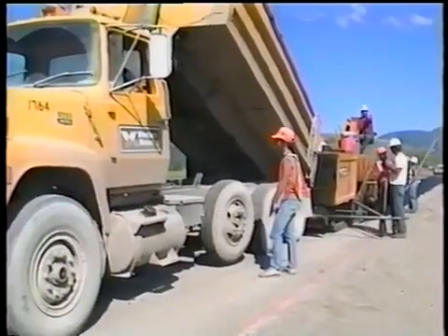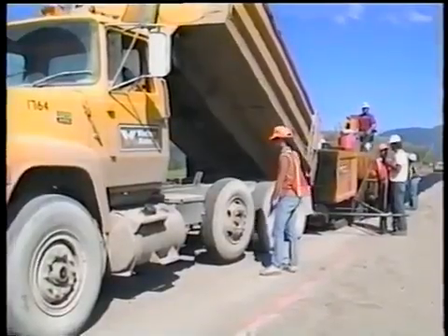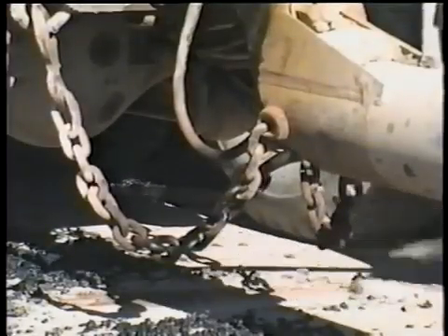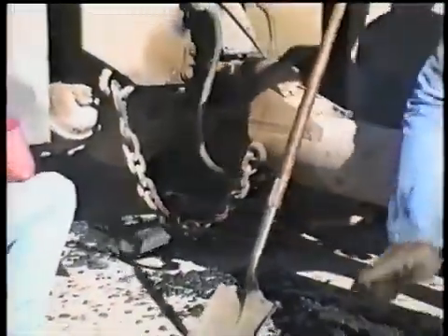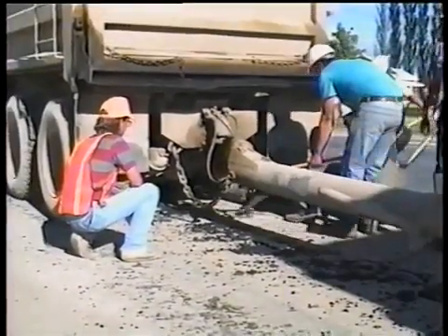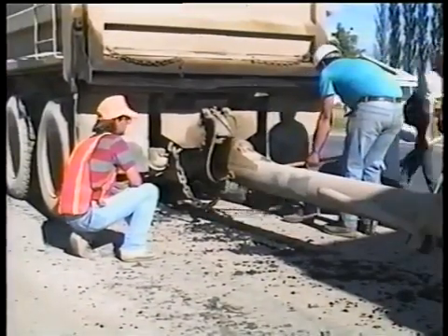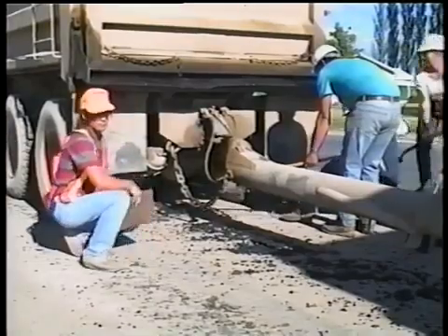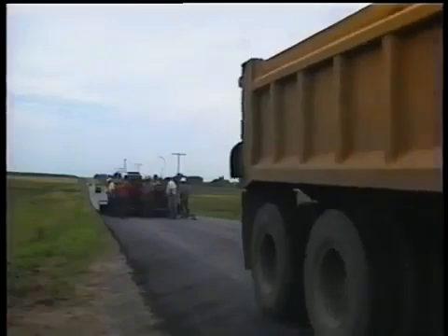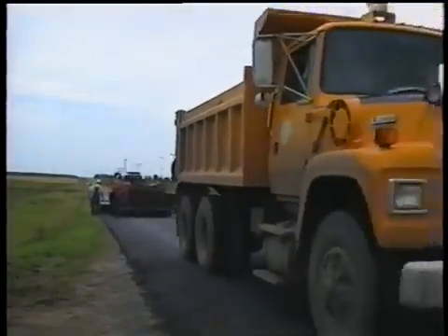When rear dump trucks are used, look around the hydraulic rams and connections too. Leaks this severe are unusual, but they do happen. If you find a leak, see that the contractor takes whatever measures are necessary to remove the spillage ahead of the paver. And of course, the equipment should be removed from the project and repaired. For safety, be sure that all truck backup alarms work properly.